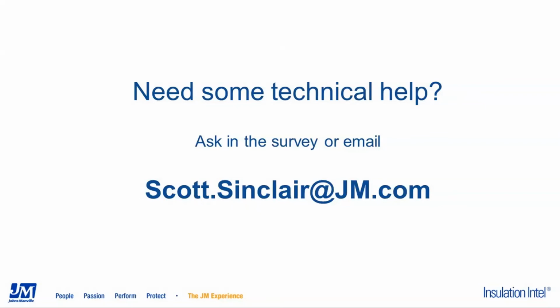Would there be any difference in insulation thickness of nominal insulation material and insulation material with the XOX inhibitor? The only thing you could really compare would be calcium silicate with and without the inhibitor, or perlite with and without the inhibitor, and in those instances the answer is no. The addition of the XOX package into both products did not change the thermal conductivity performance of either, so the thermal performance is the same. Calcium silicate and perlite have different thermal conductivities from each other, so the thickness between the two products would be different, but within the product, no, it does not have an impact.